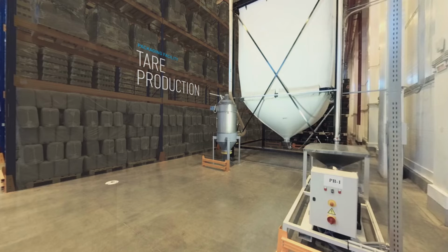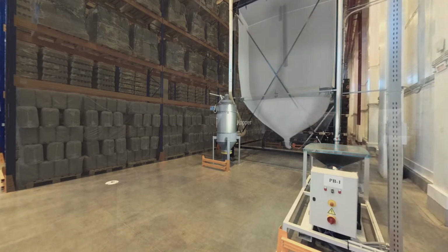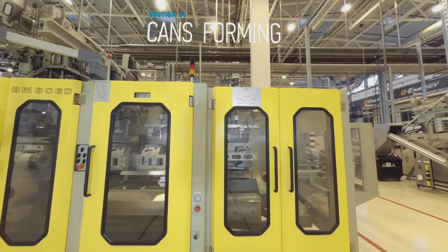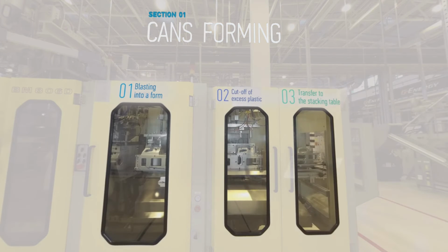Now we are moving to the rechargeable hopper. This is the place from which a fully automated production of canister filling starts. The hopper is filled with granulated plastic. Then the compressed air is forced into the extruders, where the canisters are produced. The expanding canister is blown up from melted plastic into its form.